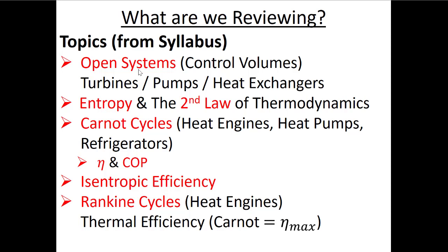We've also talked about entropy and the second law of thermodynamics. We introduced the rate version of the second law that we would use for open systems. We talked about heat engines and refrigeration cycles, heat pumps as well. The difference between the heat pump and the refrigeration cycle is really just where you're standing, what the energy benefit is. Are you heating up the hot place or cooling down the cold place? We talked about the ideal version of those cycles, which we'll call a Carnot cycle. And then we defined characterization parameters for those different cycles.